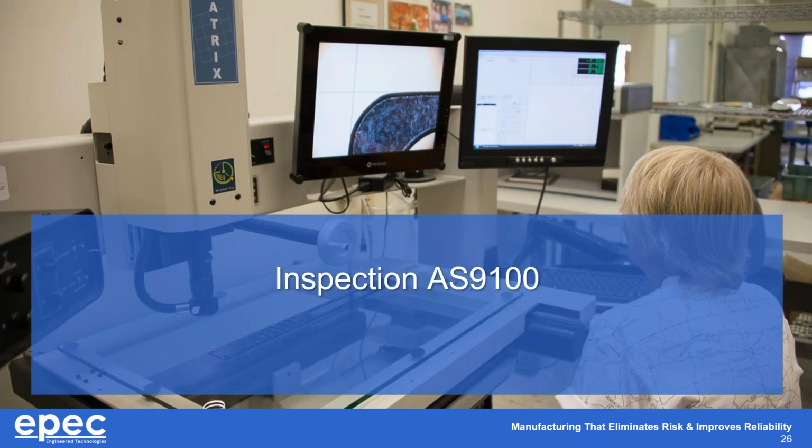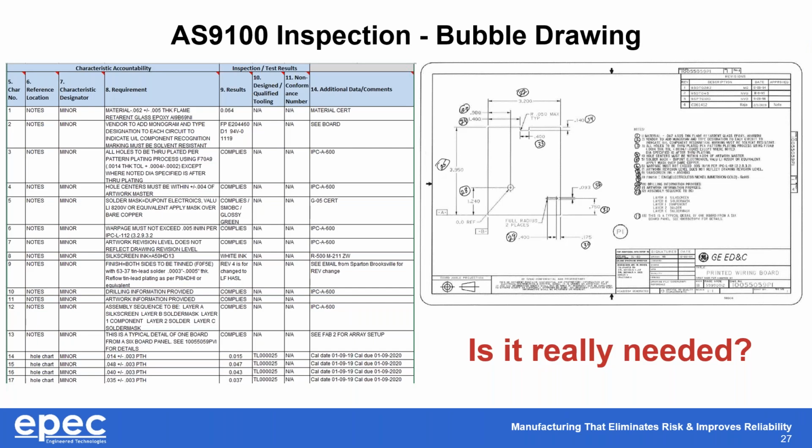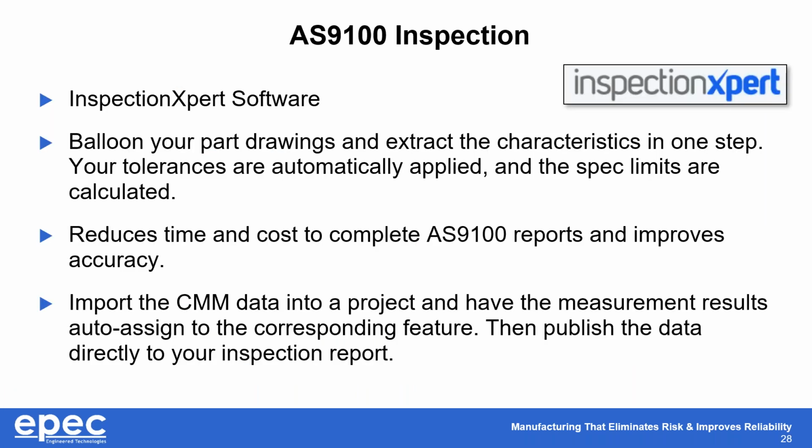The one last thing I want to talk about is AS9100 inspection. With the aerospace and military folks, we do an awful lot of this. The reason we want to talk about it is to help everybody understand why it takes so long, right? An AS9100 inspection requires a bubble drawing. On printed circuit boards, in many cases, our inspection paperwork outside of that already has that information. But it's not just the bubble drawing that's required; technically, a lot of times it's required to have inspection software, right? We happen to have a CMM that we invest in that helps us do all these measurements.